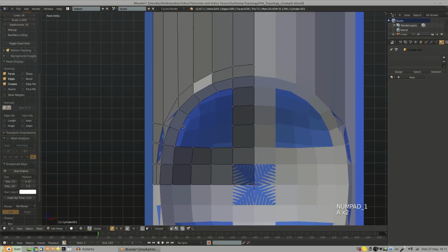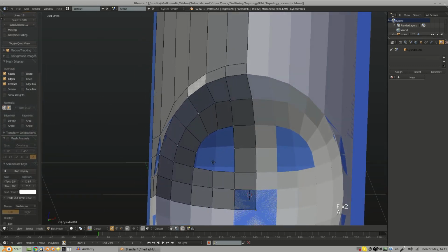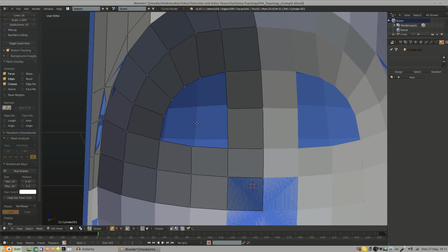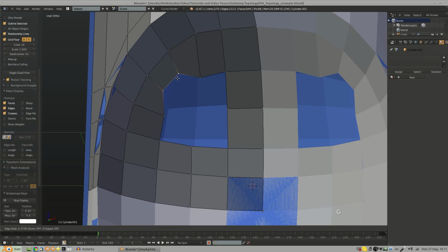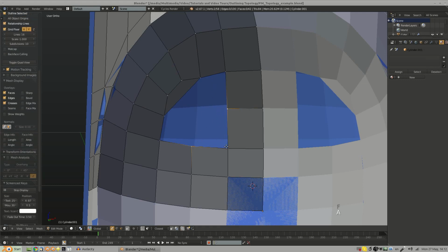So the next thing I want to do is make sure that I have another edge loop down here. So I'll scale that in, maybe scale it along itself just to make it a bit nicer. Project it again, fill that in, and then I just have to remember how I did this earlier. I'll just move this over, so I press G twice again. It doesn't show up for some reason. Fill that in there. Fill that in.